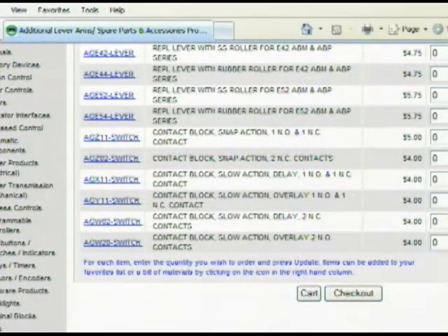Yeah, the contact blocks are kind of unique. There's different arrangements. In some applications you might want a normally open and normally closed switch, and you might want the normally open to make before the normally closed opens. And sometimes that's called slow actuation. But we also offer those types of contact blocks. In my terminology, back in my design days, we'd call that make before break, and in some cases overlapping type contacts. So those are definitely available, plus different types of operators and everything for the switches.